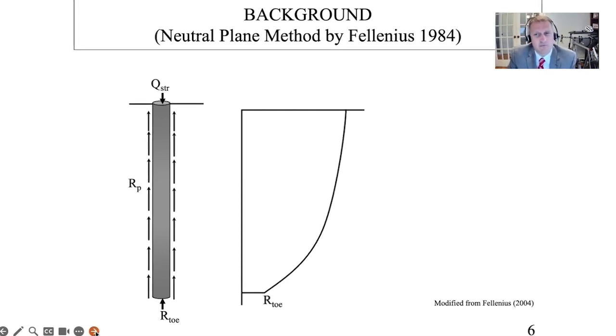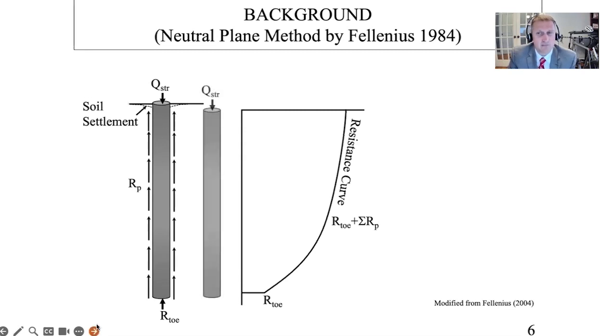For the load curve, I would start with, sorry, that's my resistance curve. For the load curve, if I did have some soil settlement, the load curve, sorry, I'm not getting to my curve yet. Taking too many steps with this animation. Okay, if we do get some soil settlement, we could have negative skin friction acting along the pile and then positive skin friction acting below this depth of the neutral plane.